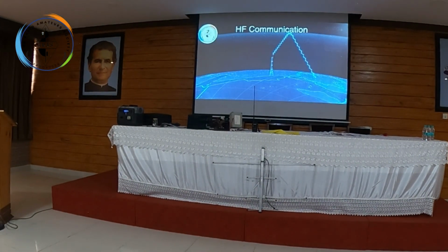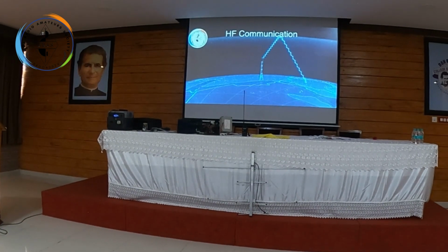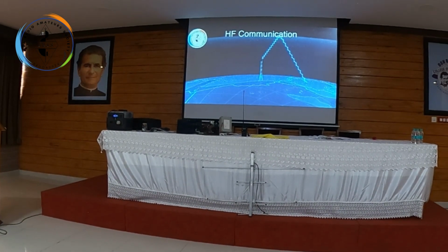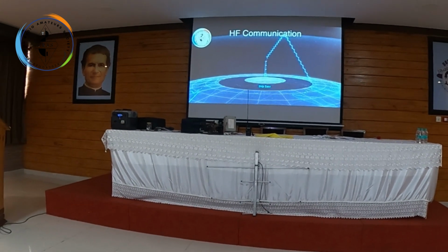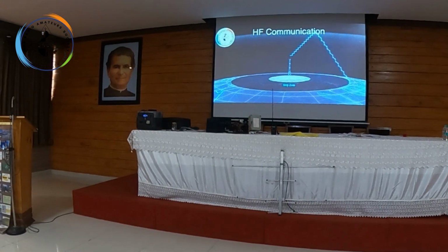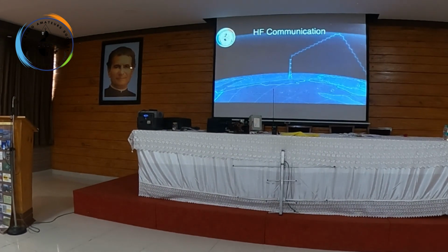A layer in the atmosphere called the ionosphere refracts the HF radio waves, making this technology work over long distance. The angle of the antenna is responsible for the coverage area as it aims the radio waves which are bounced off the ionosphere. This also creates a skip zone, where the ground wave ends and the skywave starts, where the radio waves are not present as they are not refracted into this area.